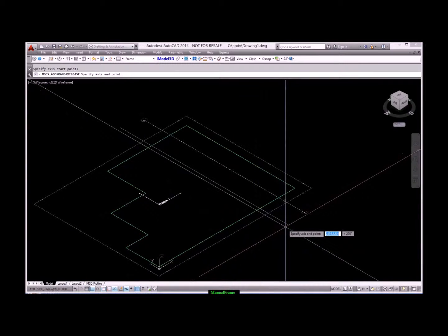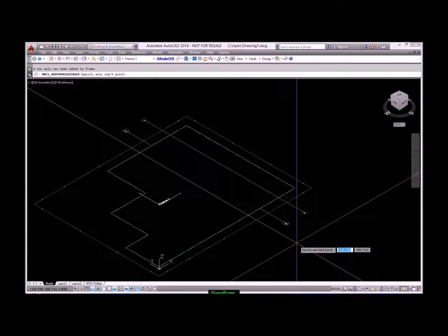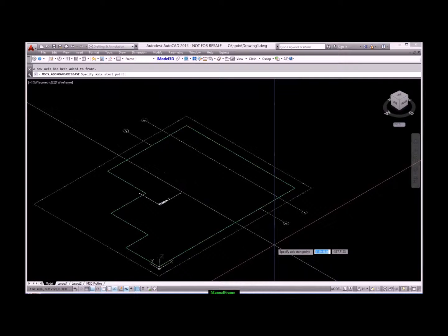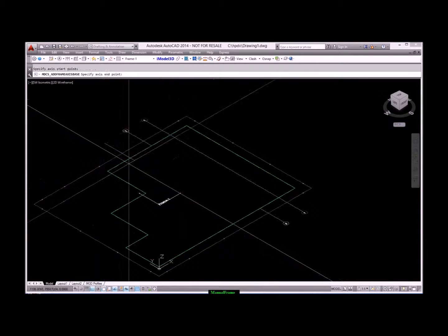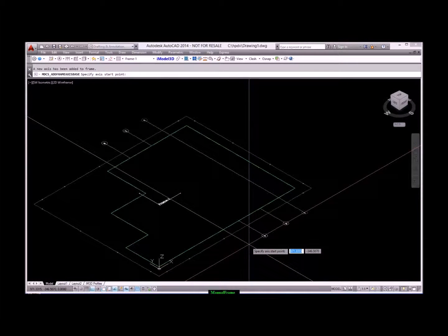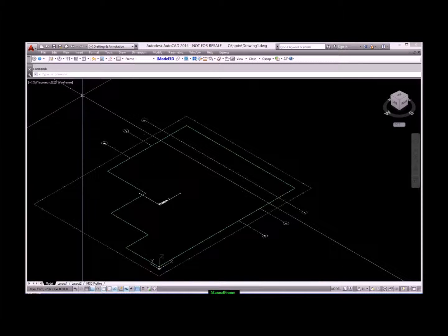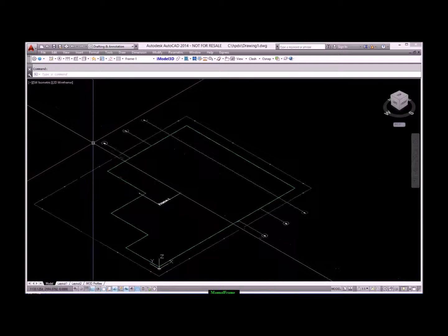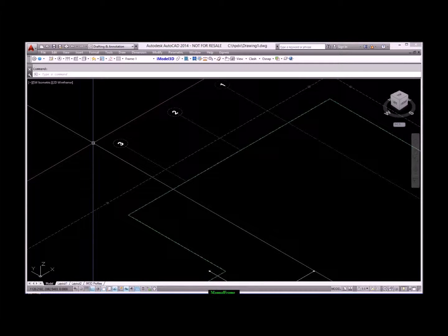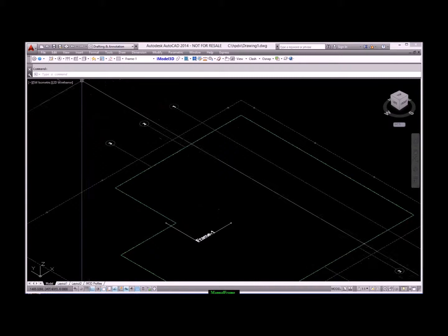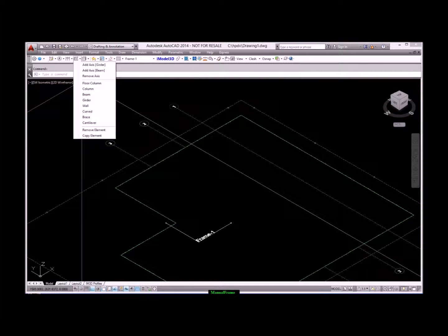Here you can specify the number of floors for this particular frame 2D as well as each floor height and slab thickness. Note that this command will not generate the frame 2D element but it will draw the frame 2D base axis and the data specified above is stored in it. After drawing this axis, you will be able to add frame elements such as columns and girders.